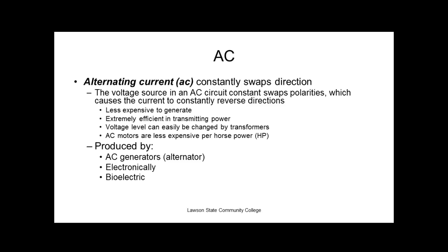Alternators. And now we have a converter in there, we call it a rectifier, by the way, that converts AC to DC. Why did they go to alternators? Well, it's so much cheaper. You might buy a 90 amp alternator for $120 something. If that was DC, it probably costs about $500. So it's a lot cheaper.